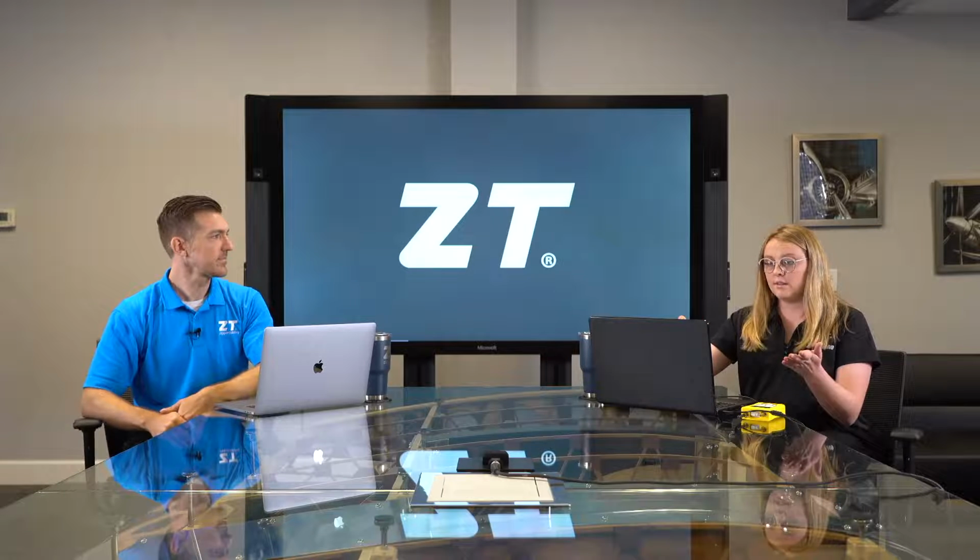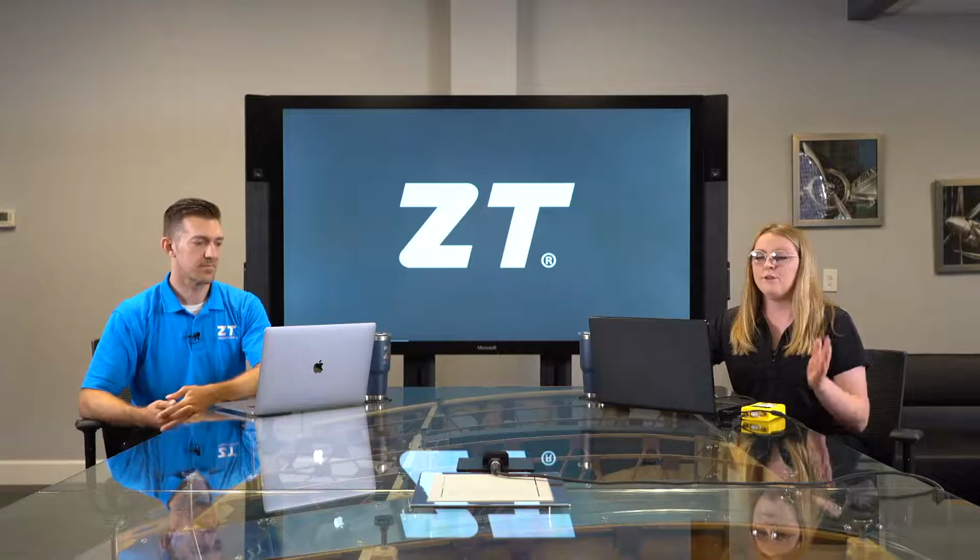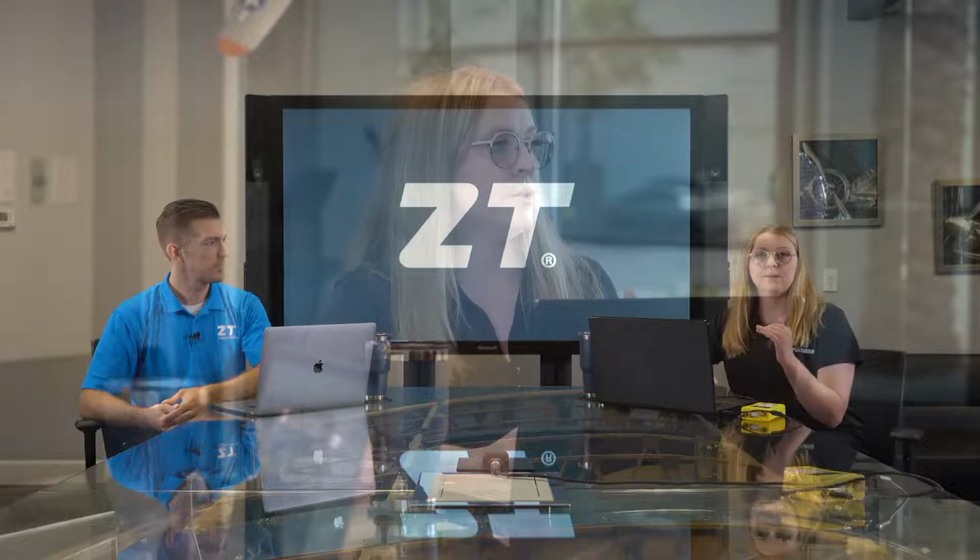Right, and what those decibel levels, that attenuation level, really means is every 3 decibels represents a 50% drop in your interference. So at 3 decibels, your interference is cut in half. You go up to 6 decibels, your interference is going to be a quarter because it's now halved again. 9 decibels, you're at an eighth, and so on and so on. So when you're looking at a graph like this one, averaging around 60 to 80 decibels, you're left with really just a fraction of that interference.